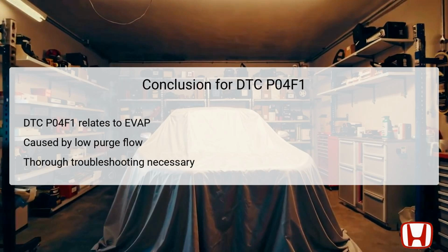DTC P04F1 is a significant code reflecting low purge flow in the EVAP system of the Honda Accord. Understanding the underlying causes of this issue is crucial, as they can involve multiple components working together to manage fumes effectively. Thorough troubleshooting, including dual checks on electrical connections, the purge valve, and associated hoses, can help locate the source